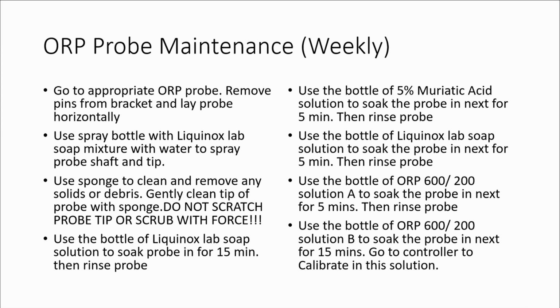We replace our head ORP probe every year. And the head ORP probe goes to the middle ORP probe, and then the middle ORP probe goes up to the aeration basin. And that's how we keep the newest probe in the most critical spot in the process.